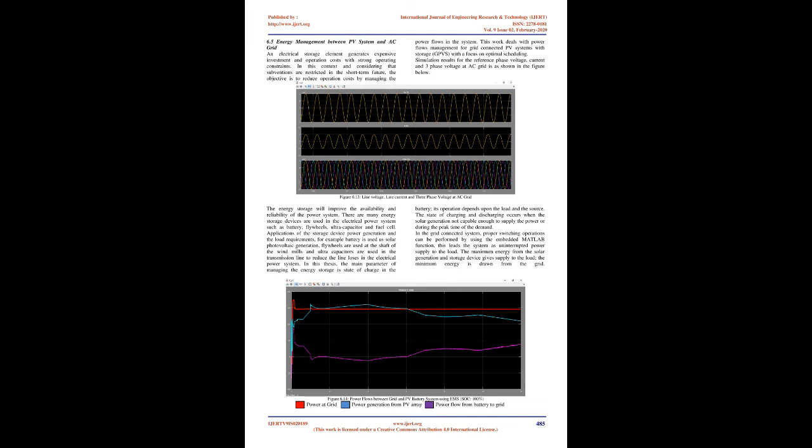6.4 Voltage source converter. The use of the three-level bridge block in an AC-DC converter consisting of a three-phase IGBT-based voltage source converter, VSC. The converter is pulse-width modulated, PWM, to produce a 500 V DC voltage, +/-250 V. The VSC is controlled in a closed loop by two PI regulators in order to maintain a DC voltage of 500 V at the load while maintaining a unity input power factor for the AC supply.